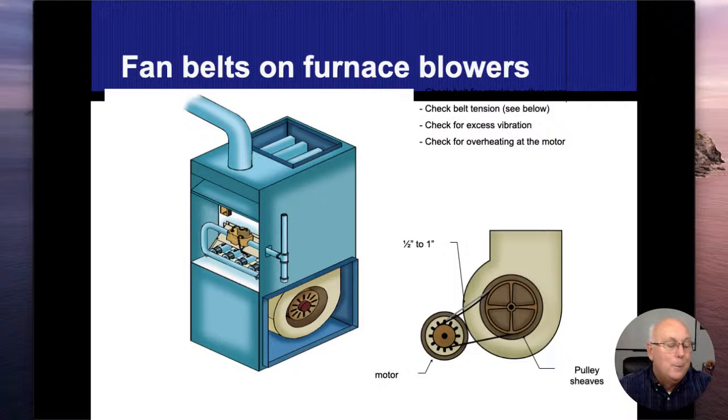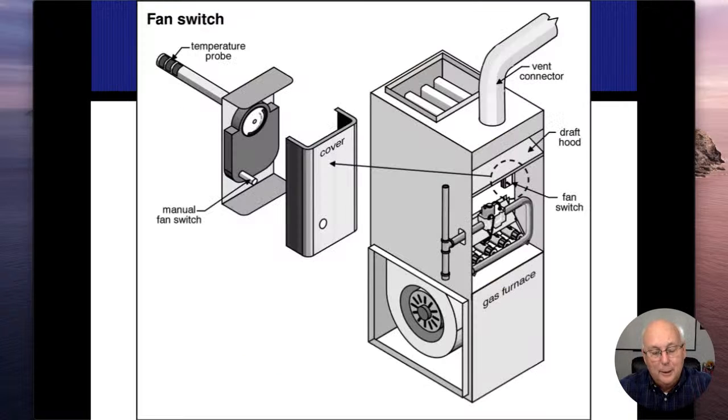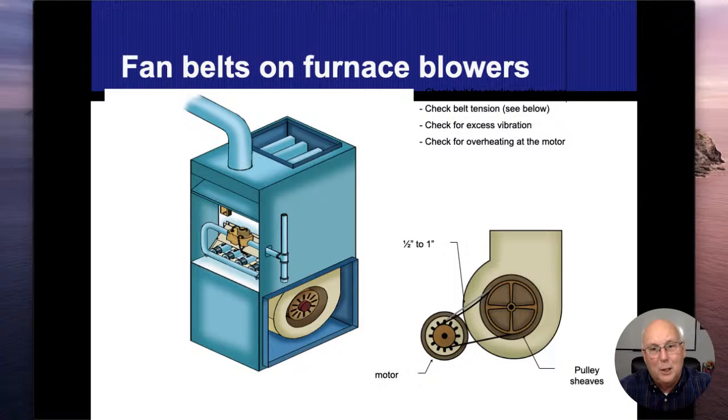All right. Older blower fans, belt-driven ones, I would encourage my client to get a belt and leave it on the ground there. Those things break at the worst times. But again, if I start seeing these older things nowadays, I would have to warn my client that this is just an older unit and it will fail eventually, and they're going to be getting an upgrade as that comes along. Everything now, these blower fans, they're all direct drive, so the motors are actually built into the fan, so we don't use belts anymore.